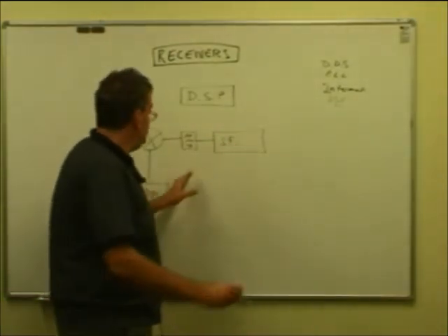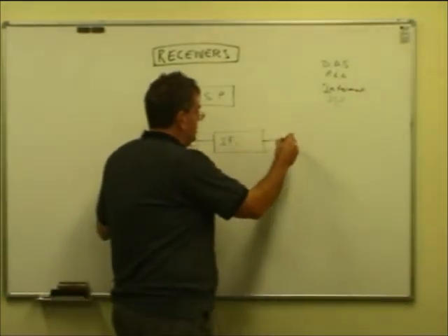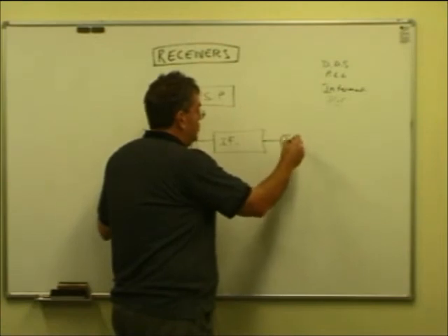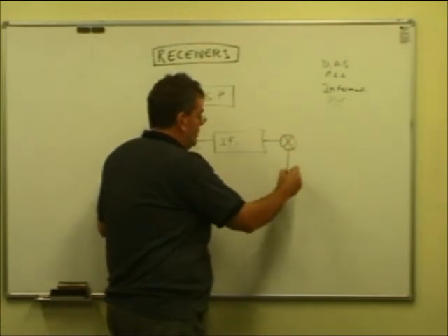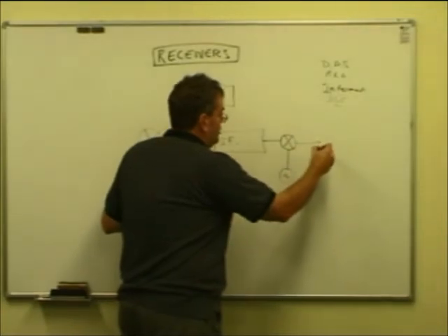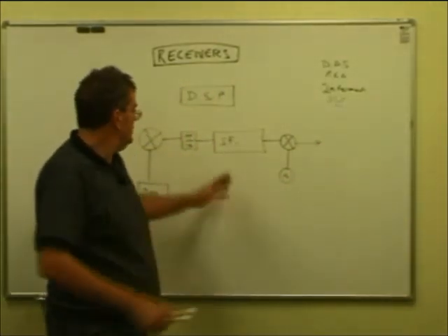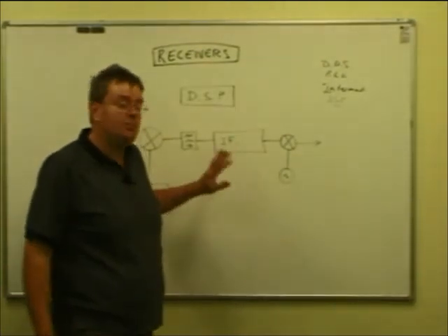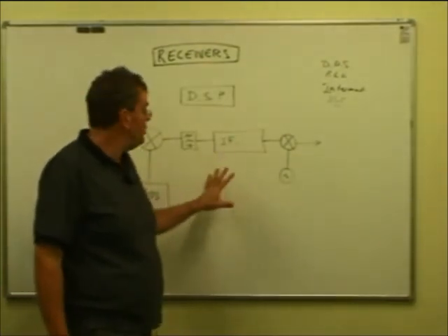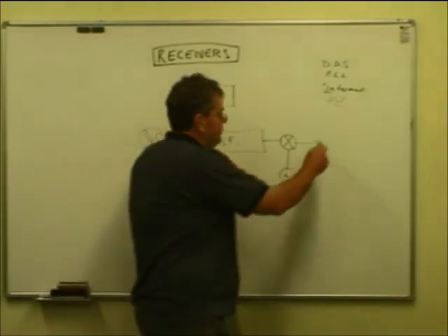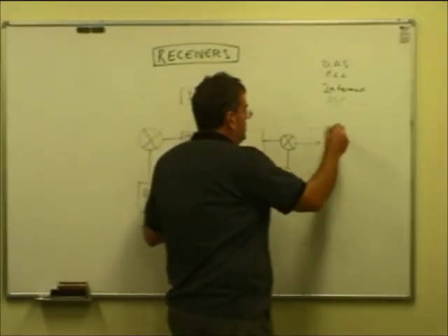What they'll often do is then go back to double conversion, for other reasons, converting the IF down to a lower frequency that can be handled easily by a digital computer system. The IF frequency in modern radios might be quite high, around 70 megahertz. They do that for various reasons. And then from then on, we're in the digital world.